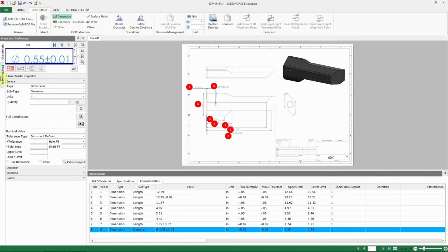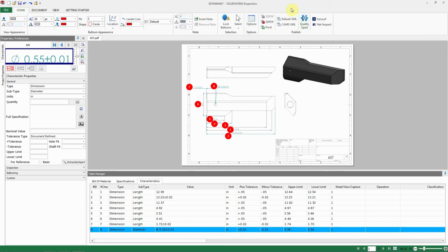There's other data I could pull into the page properties and whatnot, but what I wanted to show here is that we can take it from here, clean it up, dimension any dimensions, or add any dimensions to the bill of characteristics that we need. Perhaps bring in CMM data, and so if you have a CMM machine at this stage, we can actually import that into the project. So that's in the final inspection packet.